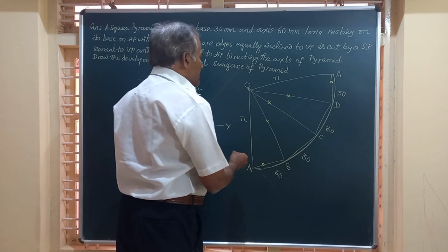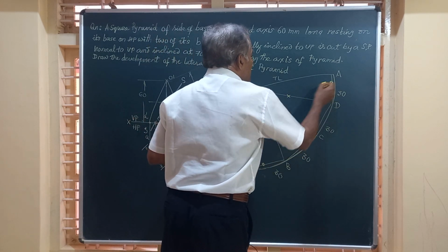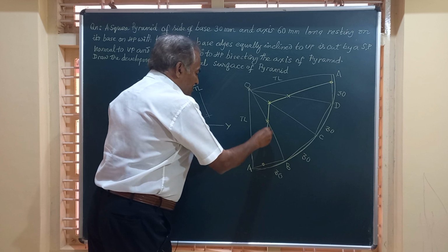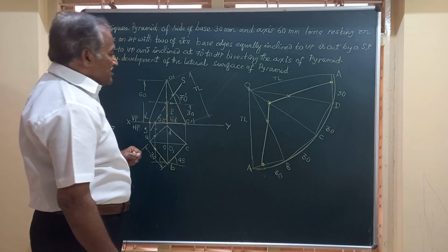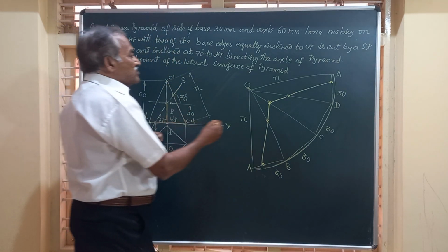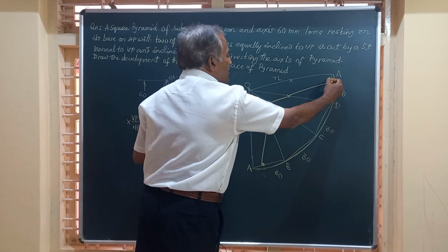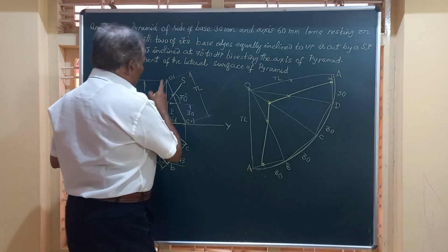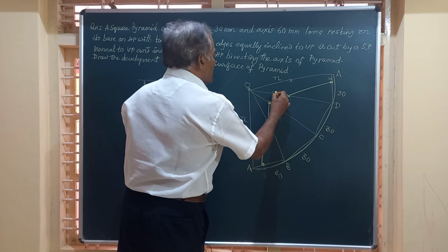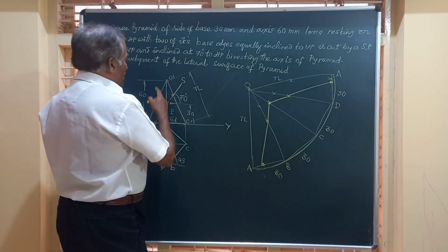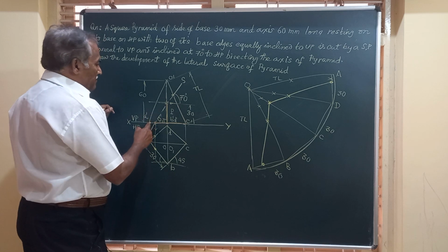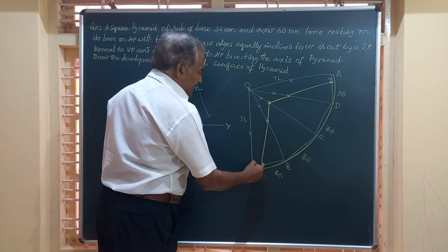So we'll join all these by straight lines. I will join these two by a straight line, this by a straight line, and this by a straight line. And here, friends, what is the portion to be shown by dark line? Let's see. OA is removed, so this does not exist. So when this is not there, you don't get this point. Then on OB and OD up to here, we don't have the part that is removed. This is not there. On OC also, you don't have that part. And finally on OA, it's totally removed and you will not have this connecting line also.